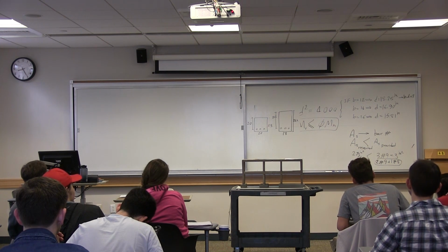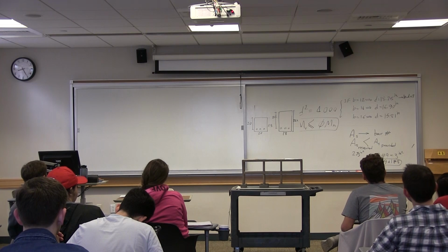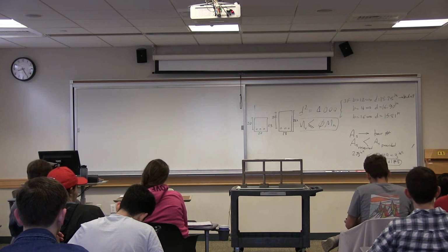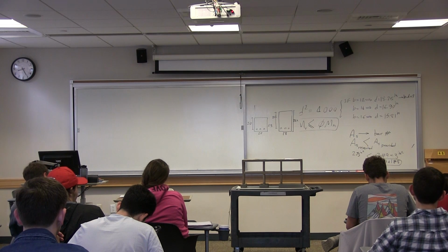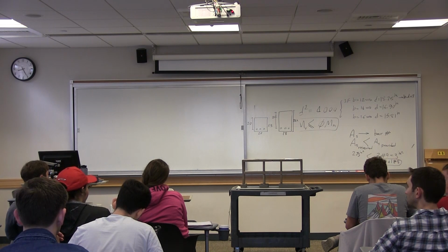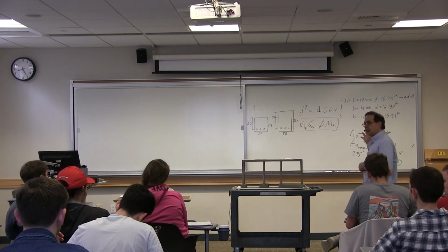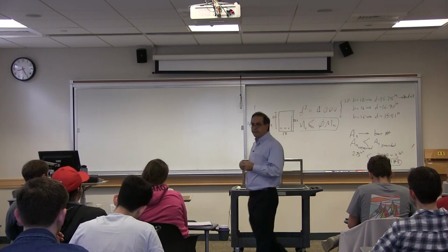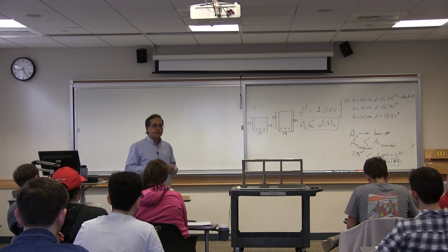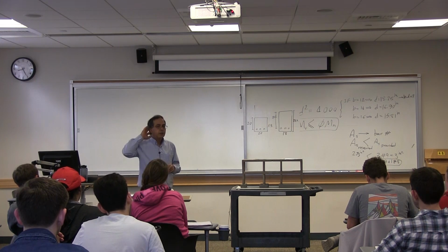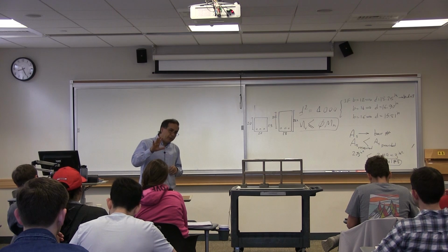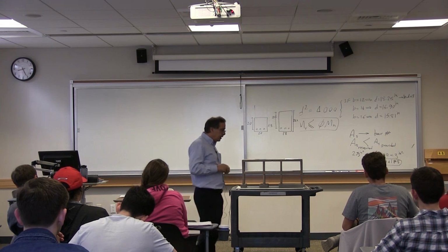Left, right? I'm not sure. What does it mean, better choice, from a mechanical point of view? You want concrete to crush before you go. That's one measure we will satisfy for both of them. Option on the right is better mechanical. Better, reason? Greater moment of inertia in the bending direction. Greater moment of inertia at one level is correct.